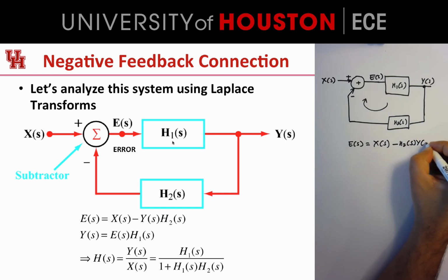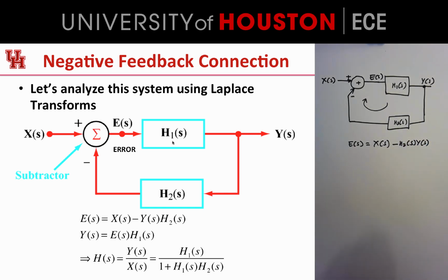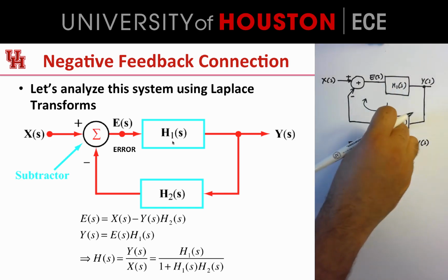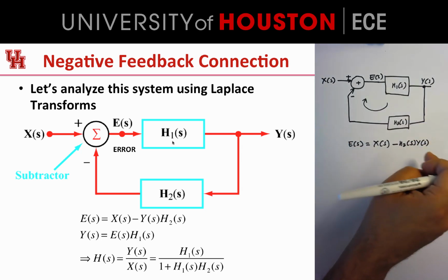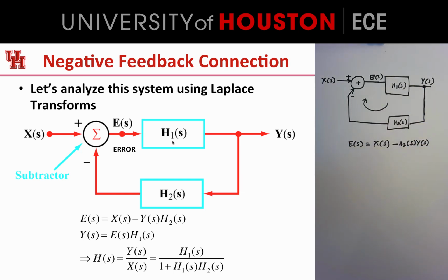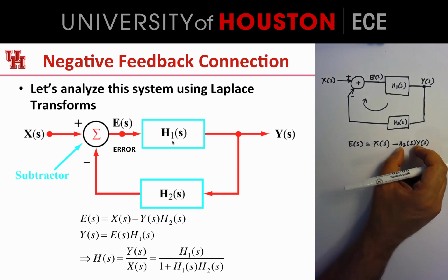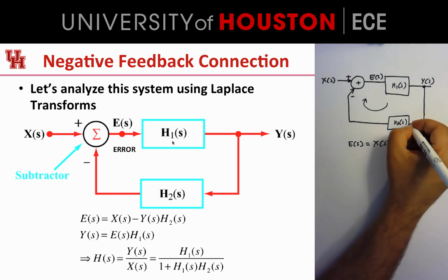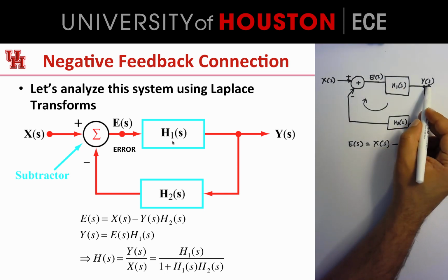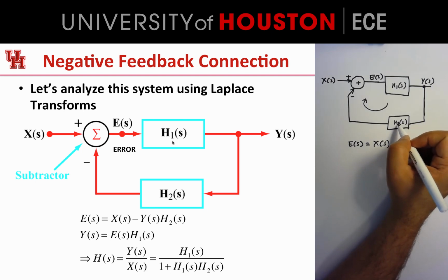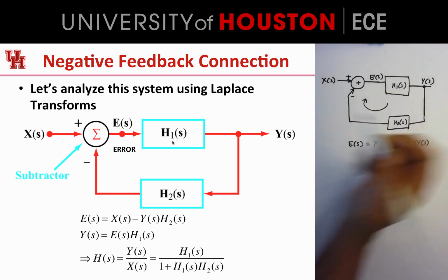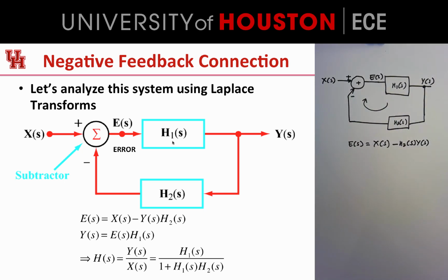Whatever the signal Y of S is, it is being processed by H2. So that's what this product is. And the beauty of Laplace transforms is that this becomes a simple product. If we were to do it in the time domain, we would take this signal Y and have to convolve it with this system, and then feed it into this differencing circuit.